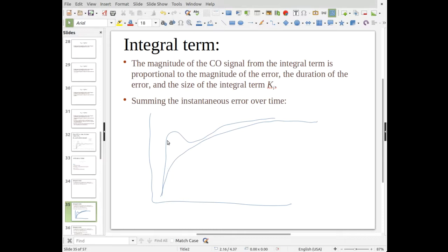As you increase your gain, you can also increase this hump and get it to respond a little bit faster. But again, the integrator piece normally slows the system down much more, and you can see the error going to 0, but it's going fairly slowly.